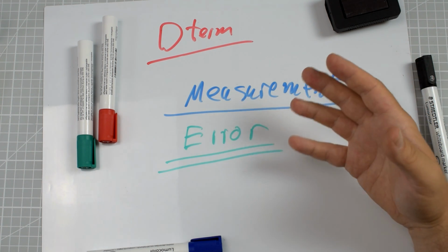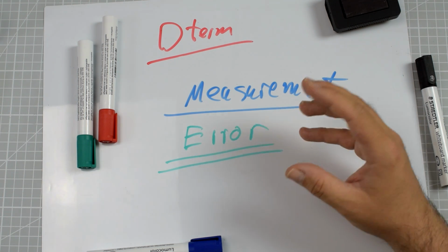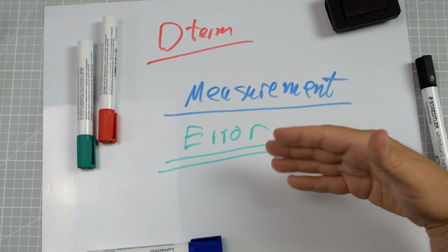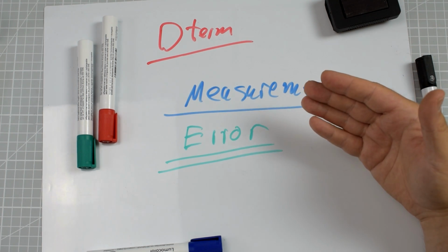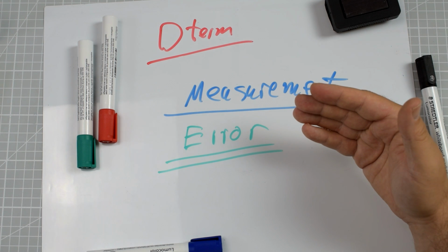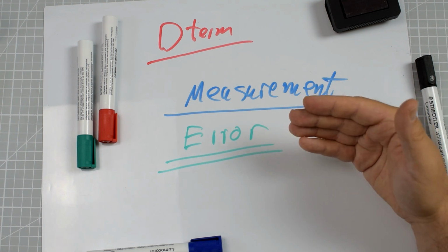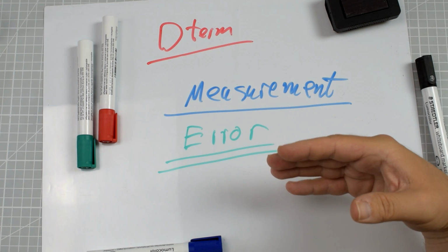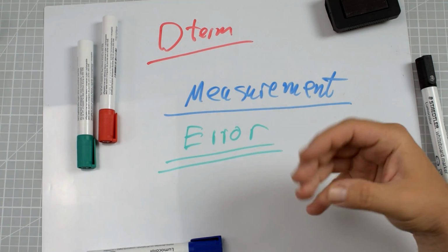Yes, there is still damping at the beginnings and at the end of the maneuvers, but the set point changes made by you, by moving, for example, the stick, if we are talking about drones, have an impact on the D term, and the response is crispier, less swooshy.